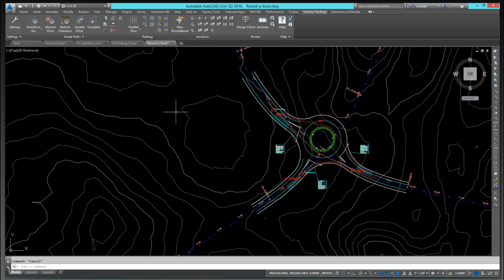And with that, it created the corridor, it created the alignment, it created the profiles. So I can now take that and take it into Civil 3D. I can then adjust the profile, I can adjust the alignment, I can adjust the stationing of the regions within the corridor, and it will adjust everything.